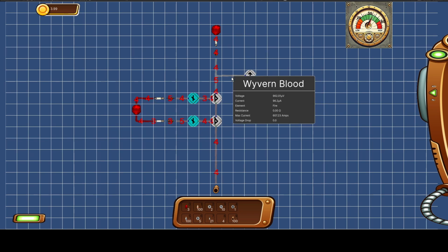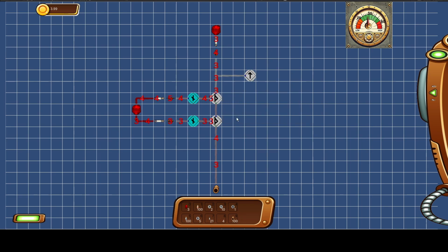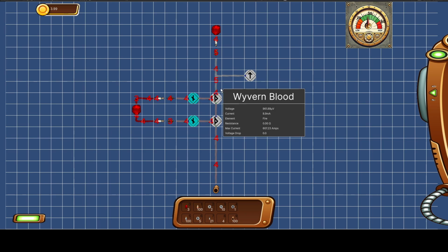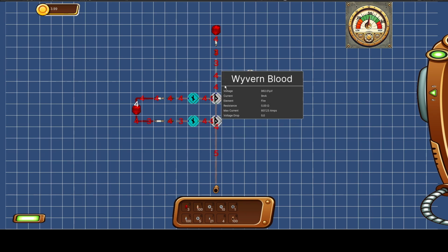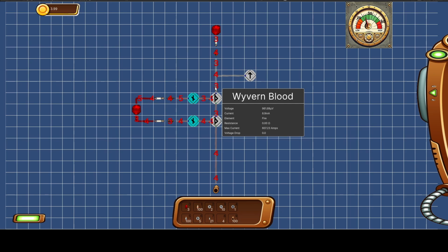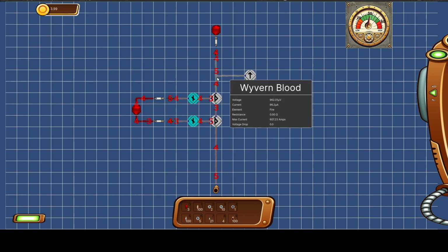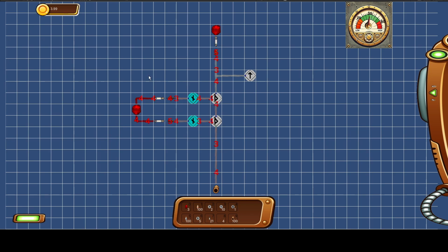So you're generally not working with a whole lot of amps. This shouldn't have this many amps going to ground. That shouldn't be happening. So we'll find out what's going on there, but you would probably be more like this, where you have this 8.9 milliamps going to ground. Same sort of thing, because you have that pull-up resistor there.